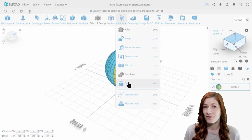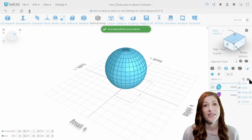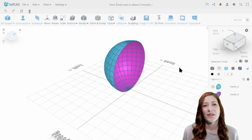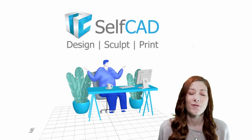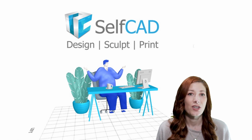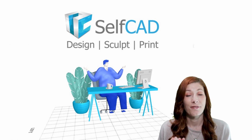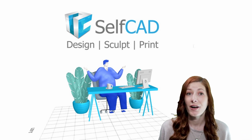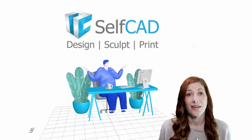You will see the same difference if you decide to split the object in half and don't add any volume. As mentioned previously, it also makes for a great tool for searching for holes. If you inspect such objects with enabled back face coloring, you will easily spot places that flash a different color from the inside, indicating that you have a hole in the topology.